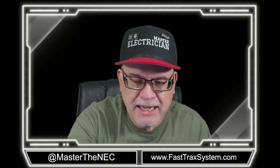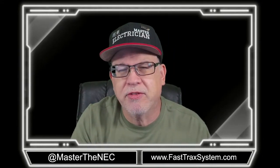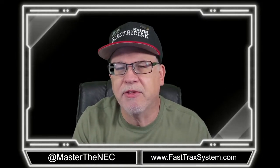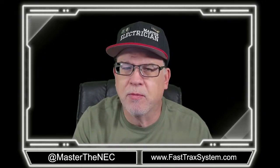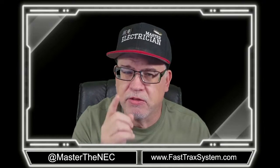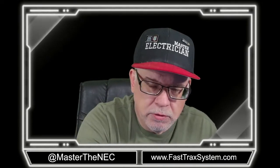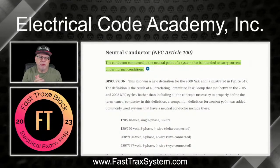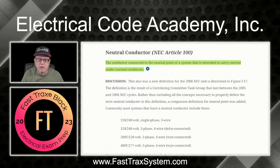All right, so let's get into it first. It's important that we learn definitions, because since the 2008 edition of the NEC, we've had a definition of neutral conductor as well as a neutral point. That's the point on the system where the neutral conductor is connected. So that kind of derives the neutral conductor. Okay, so here we are. These are definitions, out of the 2023 edition of the National Electrical Code, and this is out of our grounding and bonding series.